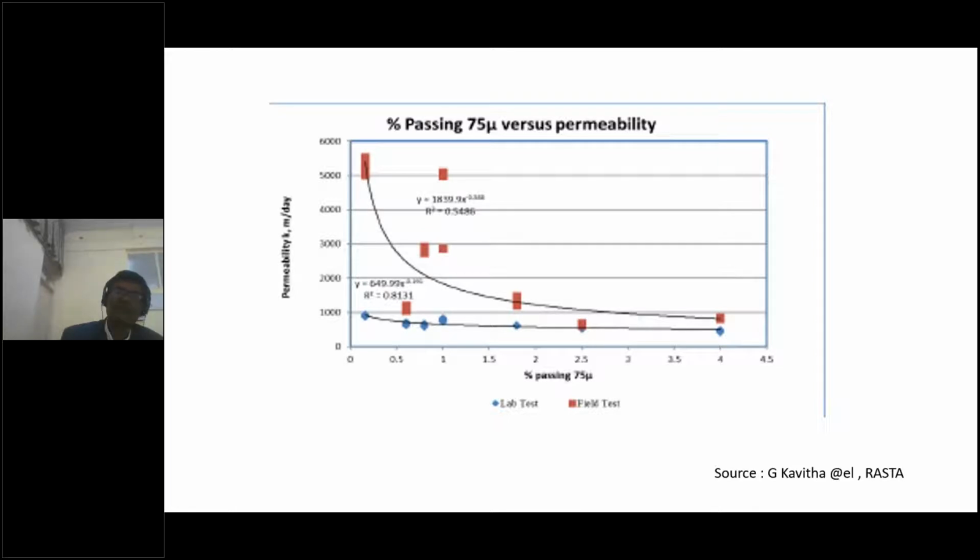If we take care of density in the subgrade layer, the majority of problems get solved. In any soil layer, embankment or subgrade, density we have to focus on. In the GSB layer, we have to focus on 75 micron control, how to control the dust and how to control the gradation, because gradation plays a very important role in permeability. So gradation and dust control is important.